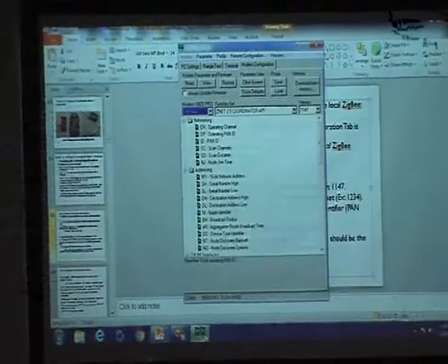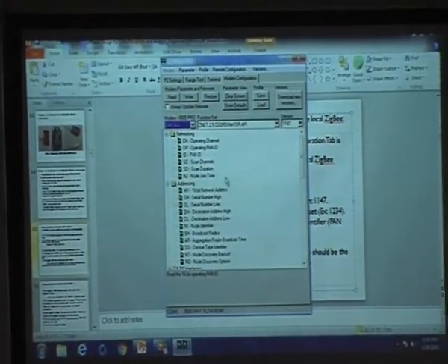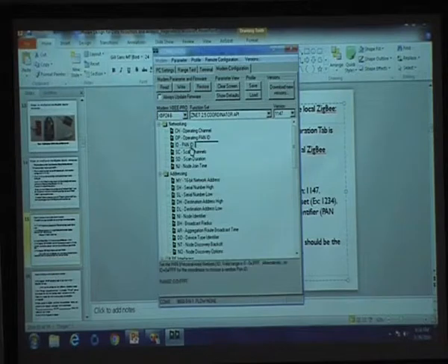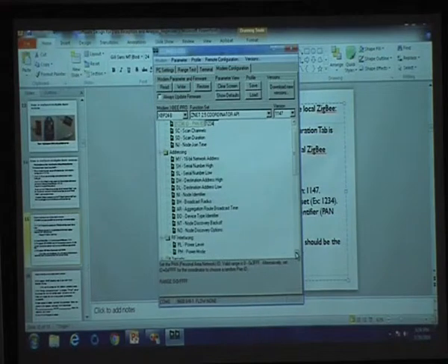So here you can select any of those values. And where can the data rate be set? If you look at the modem configuration tab, you can set the PAN ID. The PAN ID is 1234. You can set the values like this. For scan channels, you have to make sure one among the 16 channels of the 2.4 gigahertz frequency is selected as one of the channels to be used for our communication. Then for the data rate, if you scroll down, you will get the